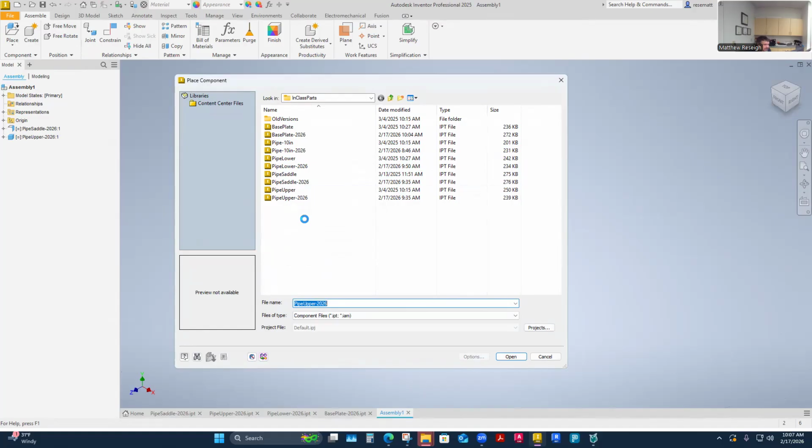So instead of doing a bunch of constraints, the only problem with that is it definitely locks down the ability to animate it. If I'm building an assembly where I do want to do some animations, then I need to control those constraints, right? Because to do animations, we drive the constraints that we build. So this isn't how I would do it if I knew that was my output. This is just down and dirty, easy.